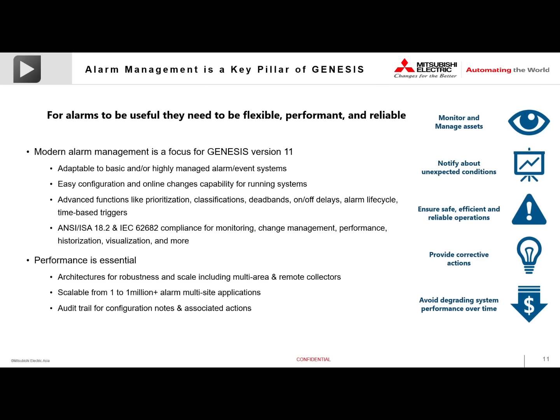Similarly here, there are some changes to alarm management. We have rewritten our alarming server as well as our historian, and that has helped us to expand the scope of how many alarms we can process and manage within one instance, how fast we can do it, and what the data types and alarm types are. So all these flexibilities and additional functions like prioritization, classification, deadbands, all those things are already included inside here.